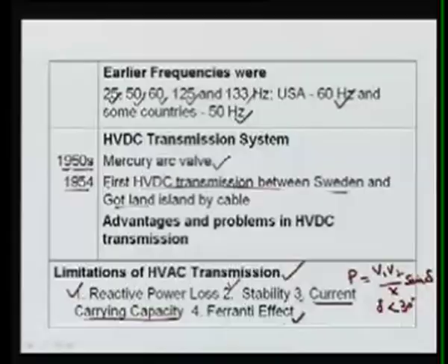This normally happens if your system has collapsed or you are energizing the line from the sending end, and the receiving end is lightly loaded or has no load. Your receiving end voltage will be higher, and your protective devices will sense the voltage and again trip your transmission line. So it is not possible unless you control that voltage. So this is your Ferranti effect.